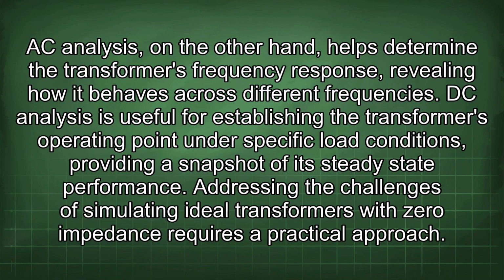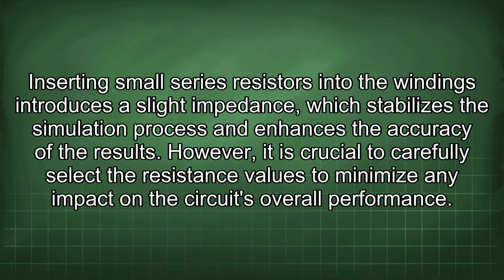steady-state performance. Addressing the challenges of simulating ideal transformers with zero impedance requires a practical approach. Inserting small series resistors into the windings introduces a slight impedance, which stabilizes the simulation process and enhances the accuracy of the results.